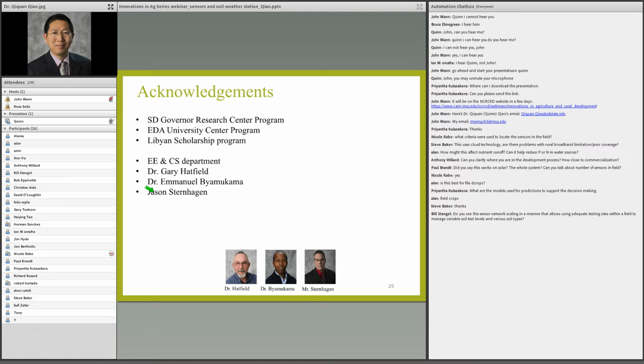And for the data communication, we use LoRa. LoRa is known to consume very little power. So only the supernode is powered by solar. The sensor nodes will be buried in the field, so they use batteries. They can be coin batteries, since the power we use is so small for these sensors. So the battery can run a long time.